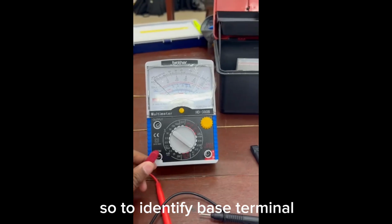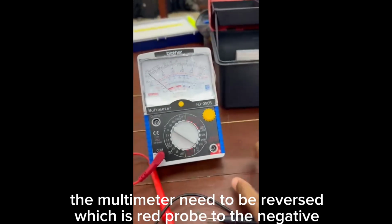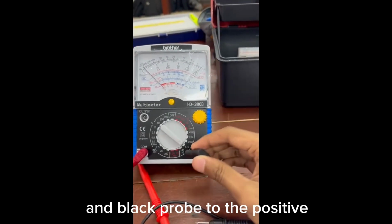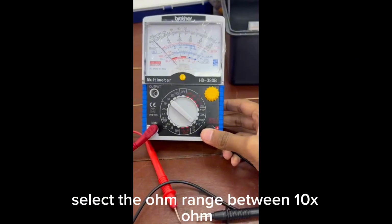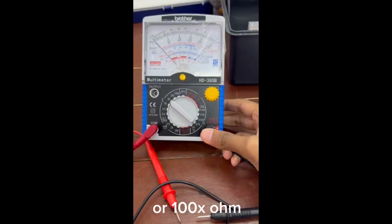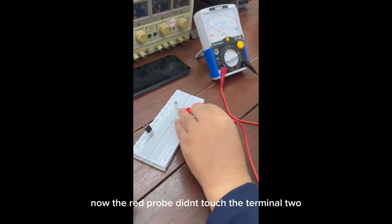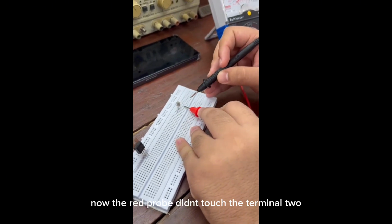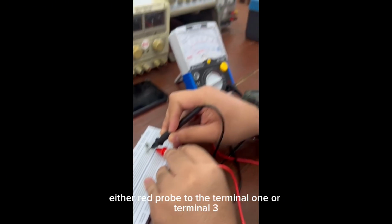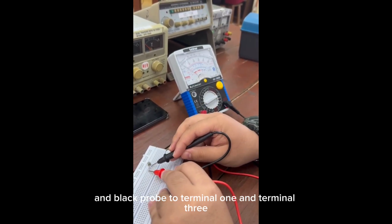So to identify the base terminal, the multimeter needs to be reversed, which is red probe to the negative and black probe to the positive. So select the ohm range between 10 ohm or 100 ohm. Now, the red probe and black probe don't touch terminal 2. Either red probe to terminal 1 or terminal 3 and black probe to terminal 1 and terminal 3.